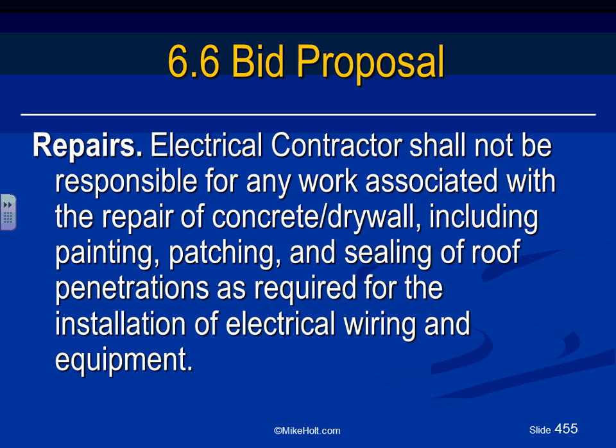Repairs. Electrical contractor shall not be responsible for any repair associated with concrete. So if you made holes in the concrete or drywall, are you going to be doing that or would somebody else? The practice, guys, is if you make a hole, you have to patch the hole with the equivalent material. A lot of contractors, when they mess with the roof, have an association with the roofers because of insurance.